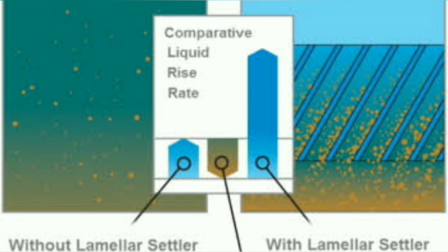Both it reduces the area that we require for a sedimentation tank, and also it has the added advantage of reducing the coagulant dosage. And also already existing sedimentation systems can be retrofitted and converted into tubular or plate settlers. And it requires less filter backwashing because of the tube settlers, which means it reduces the load on the upcoming unit, that is, the filters. And tube settlers increase the allowable flow capacity by expanding settling capacity and also increasing the solids removal in the settling tank. It has many advantages when we compare with the regular sedimentation tank.